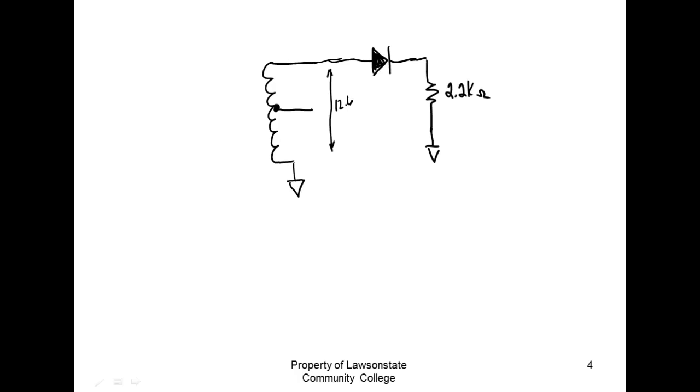Okay, so calculate this for me. What voltage should I get out? So we're using 12.6 volts, even odds are that's not what it is, right? You understand, but it's going to be close enough. And this is what you do when you calculate according to the values that you're using. It's a 12.6 volt center tap transformer. I'm using the whole transformer.